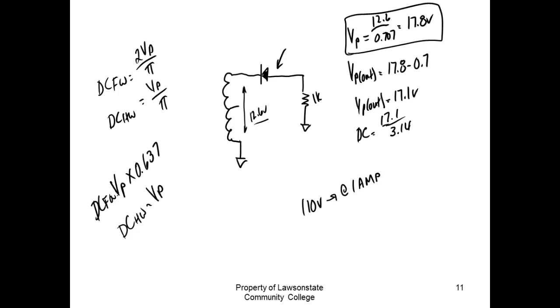So the book gives you 1/2 of that, and what I'm trying to say is that 2 V peak over pi is easy to remember, because that basically comes right out of the radians formula, if you're familiar with that. So for full wave, 2 V peak over pi. For half wave, it's V peak over pi because it's 1/2 of the other one.